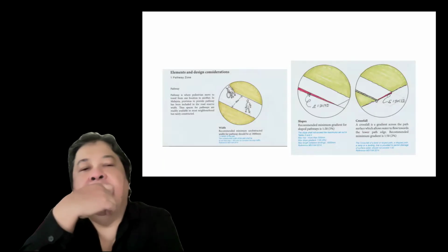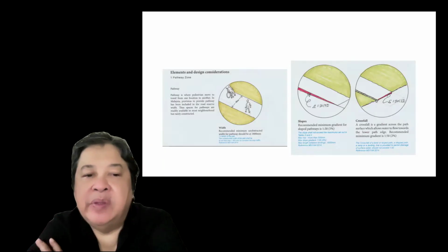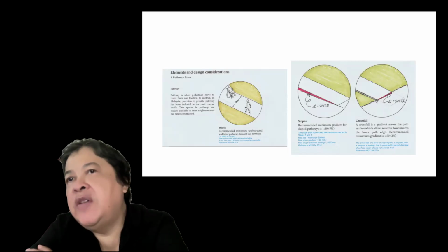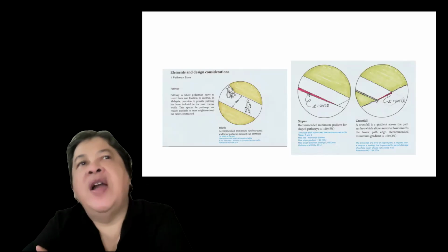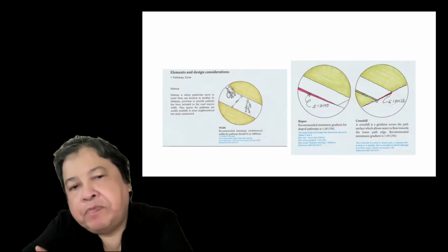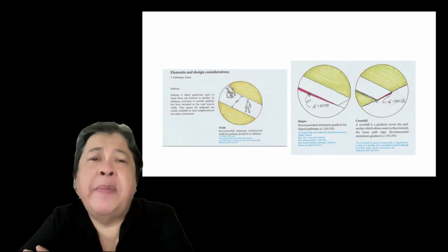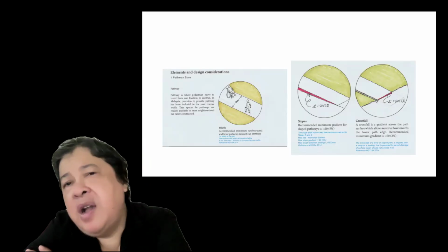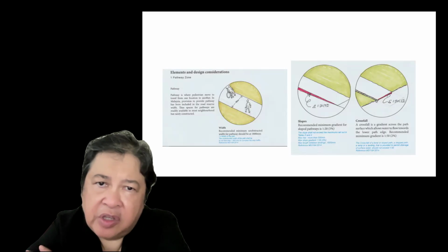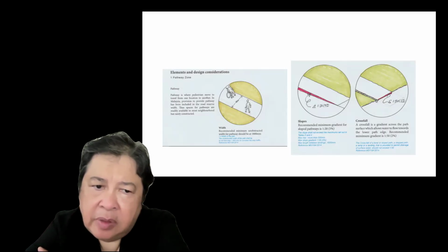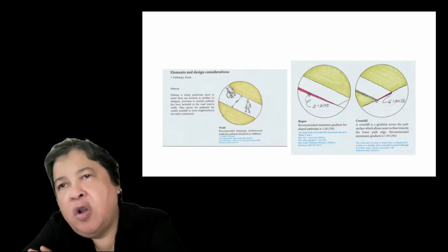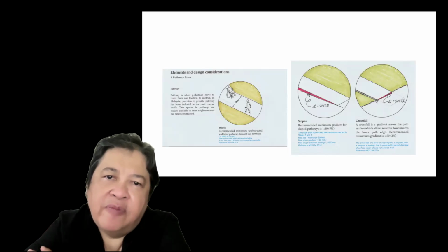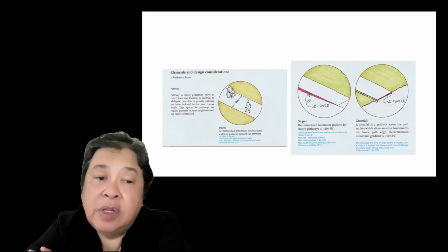What we need to consider is that the street environment, the pavements, should be wider than just 900 millimeters, like for internal corridors, even small corridors. But we do find sidewalks that are just 900 millimeters, for example in Jalan Tunku Abdul Rahman, because of its heritage area. But there need to be guardrails so that people don't fall off the curb in such a busy road environment. What is great is if we have a buffer of landscape and then the inner part of the pavement is at least 1.5 meters, or the best would be 1.8 meters.